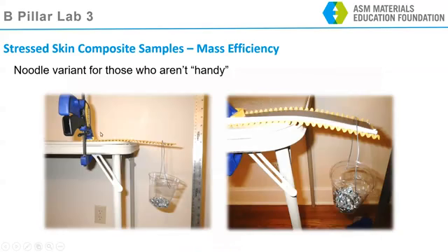So here's a close-up of my lasagna noodle. I've clamped it to my table. Okay, my duct tape is on the surface that becomes convex, on the upper surface here because I'm doing a cantilever beam test. Now one of the tricks about this lasagna noodle is the ridges on the side actually do a good job of hanging onto the wire hook for my cup. And in this case I've used hex head nuts as my weight. And I do get a deflection that I can measure.